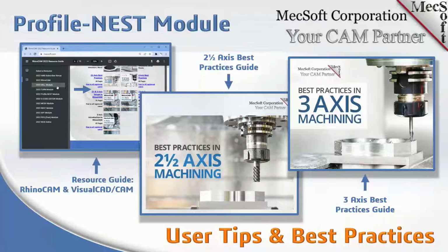And then finally, as we go along, we'll be recommending some tips and suggestions on how to set up your nest, how to do your geometry, and how to do your profiling operations. We also have additional best practices guides for both 2-axis and 3-axis. I recommend that you go back and look at the best practices in 2.5-axis machining.